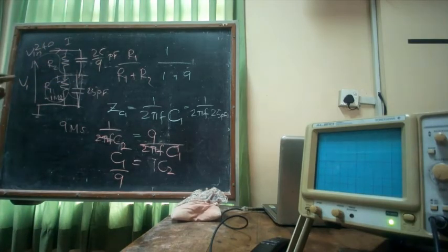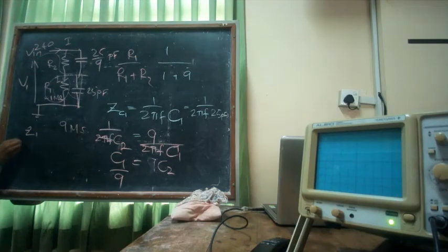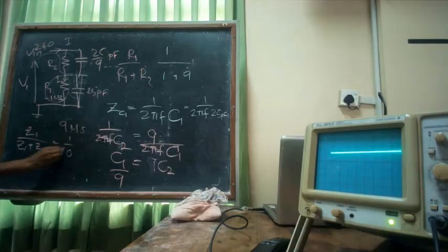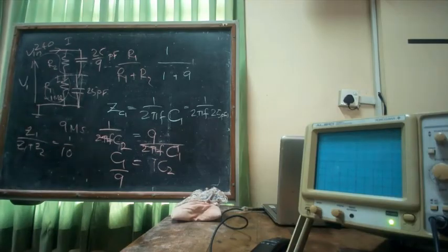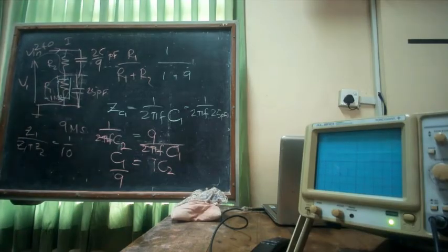If this is the case, at high frequencies also, you will have the same kind of ratio. In between frequencies, they will have a combination of impedances so that the total impedance will again be, with C1 plus C2, basically both these will be equal to 1:10, if I ensure this. Now the issue is this: I can very nicely control this. Once it is there, it's there, very precise.